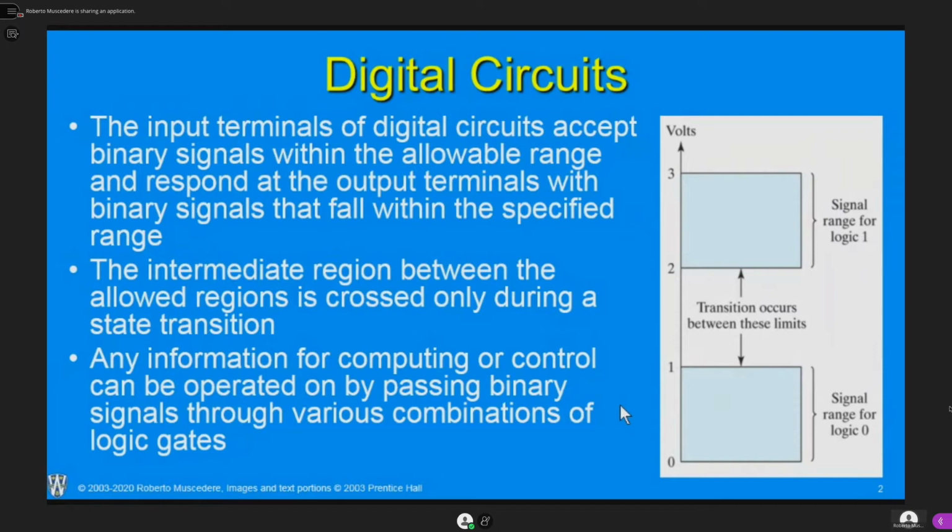So again, just like with analog circuits, you guys, I believe you guys did your analog project at some point in electronics 1 or 2. You can't just arbitrarily connect things and not expect there to be some kind of impact, right? So again, with digital logic, we have some flexibility there. I can connect maybe 4 gates to one output of a gate and not really worry too much. But with an analog circuit, just connecting something to the output of an analog circuit or something else to the output could change its characteristics if it's not designed correctly. Okay, so again, this is another reason we like digital circuits. Again, noise margins and these loading issues.